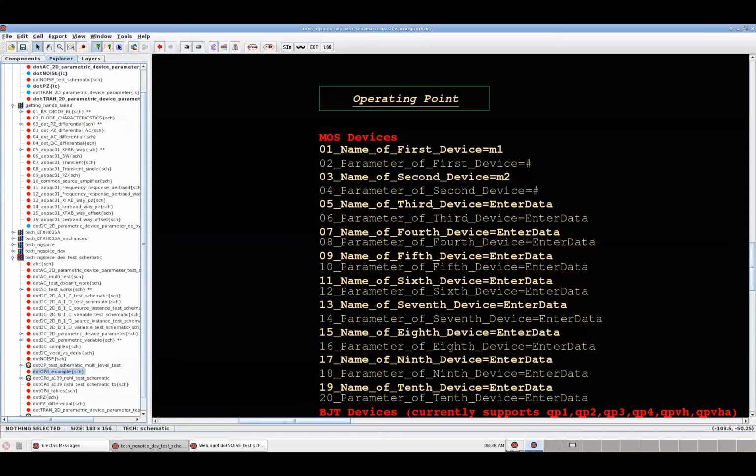So the way I remember, back in Cadence, you used to have the instance contribution of the noise of each instance, and you can get spot noise, integrated noise. But as far as ngSpice is concerned, not that I'm aware of at the moment, that you can find this for the individual device.